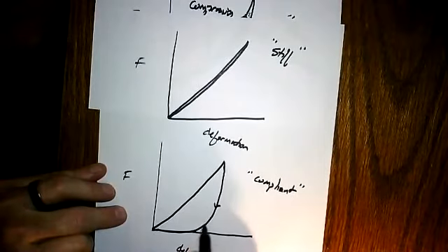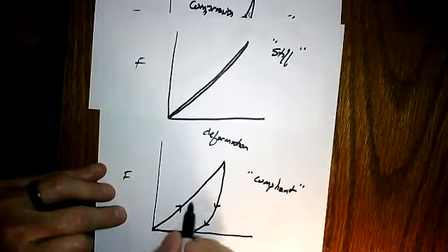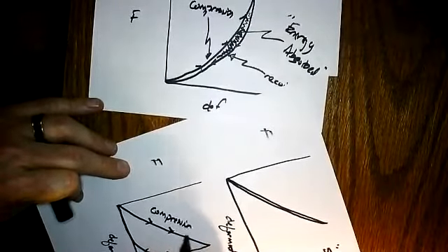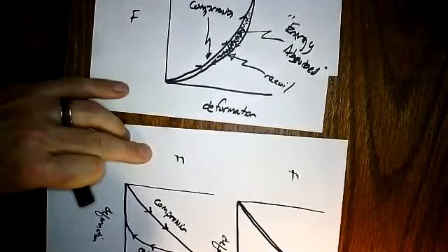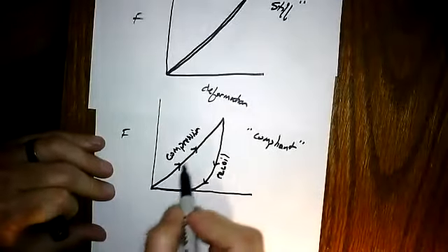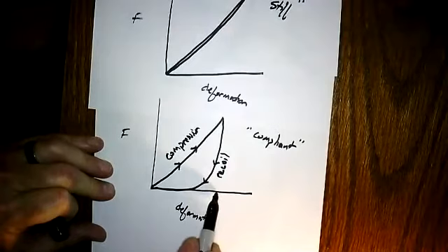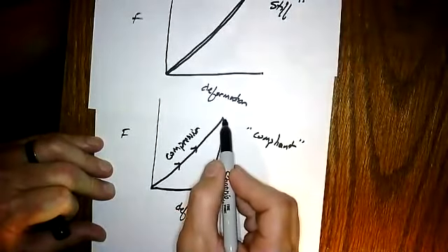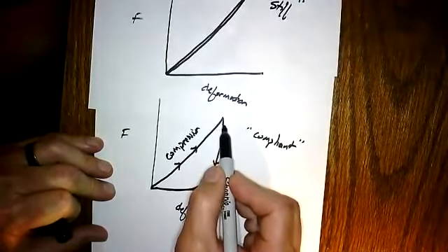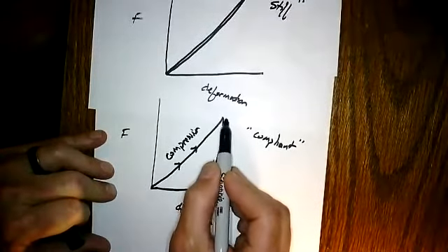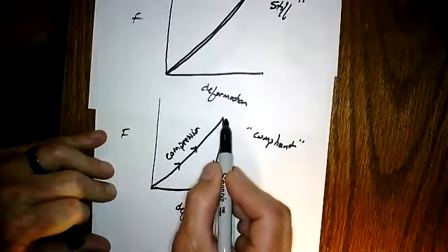So again, we're going in this direction in time, and this is compression. And this is recoil. Okay, compression. A force is being applied, we're having more deformation, but then once the material is compressed, it's pushing back upwards on the missile to move the missile upwards, because we're going to have max deformation here, we're going to have zero velocity.